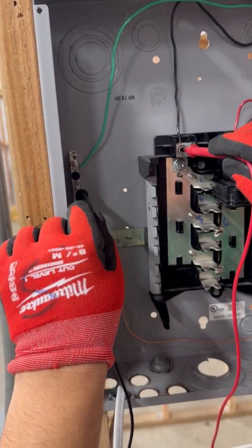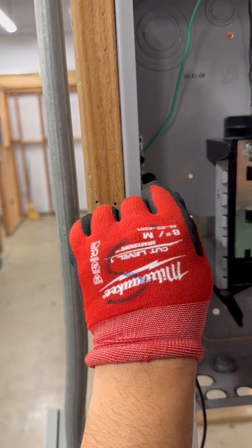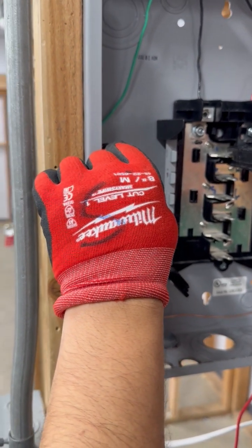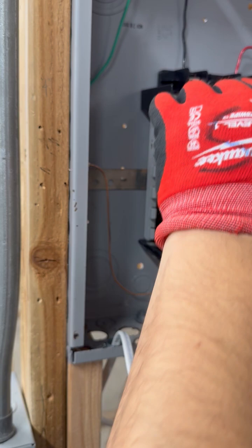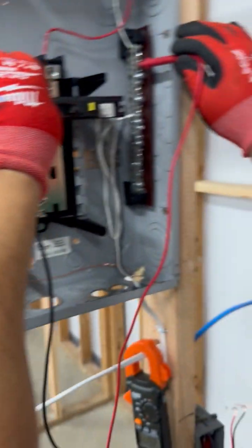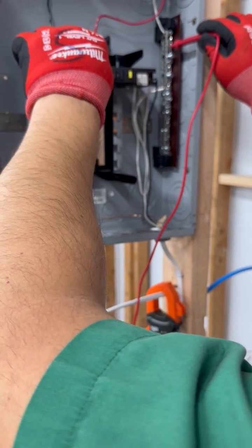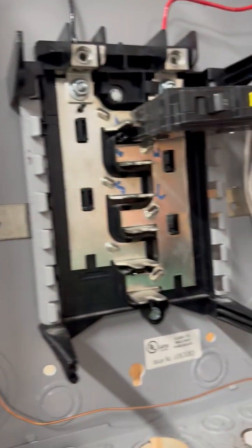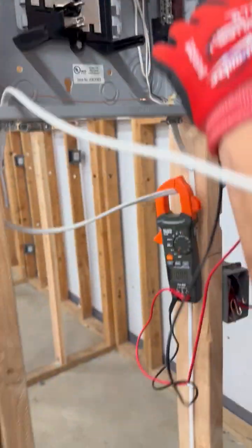I'm going to come over here to the ground, give a ground to line 1 check, and give them the voltage, 120, and then a ground to line 2 check, and I got 120. Then I'll tell them, give me a line to grounded neutral. Shift over again. Got my grounded neutral bus, and I got it to line 1, 120. Line 2, 120. And I show them the nuances of the standard procedures for checking.